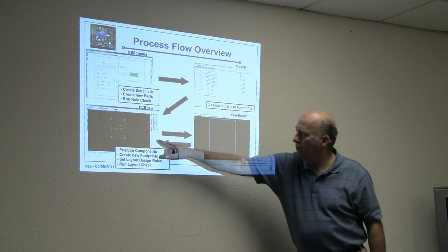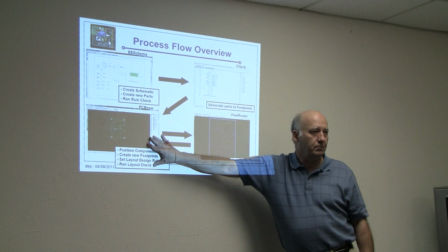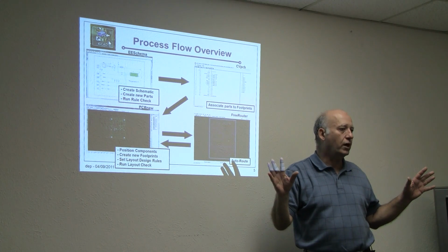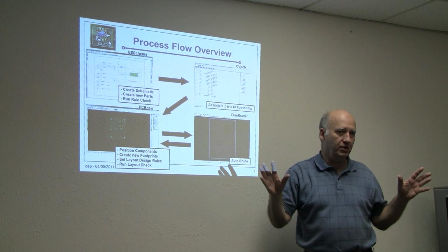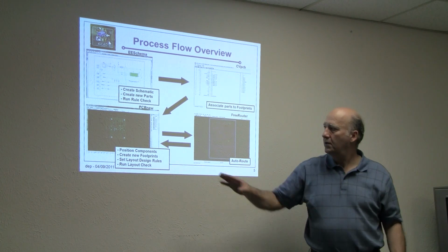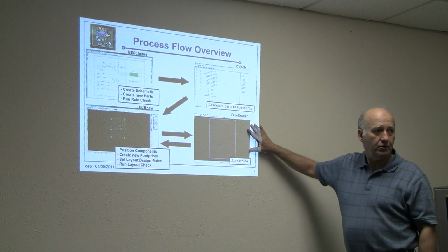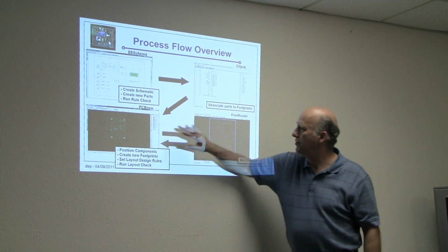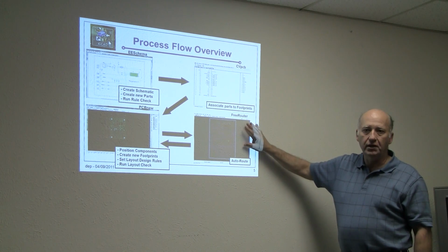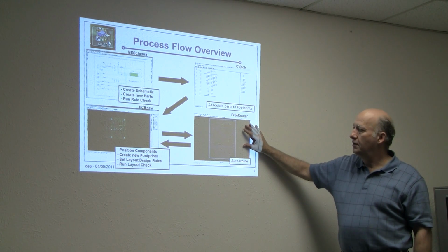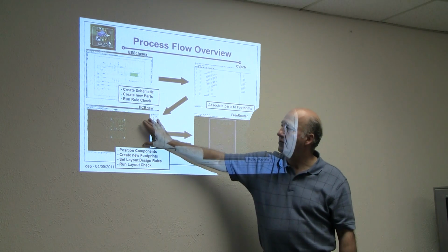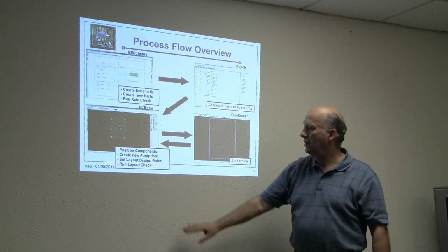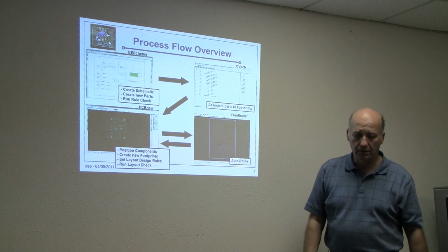Now, when you put the parts out there, you haven't done any actual tracing. You haven't done any of the wiring of the parts together on the PCB yet. That's when you go to the auto router, and we will export a file from here to here, which will then auto route it for us, and then we'll bring that file back to here and touch it up a little bit and run our layout checks.